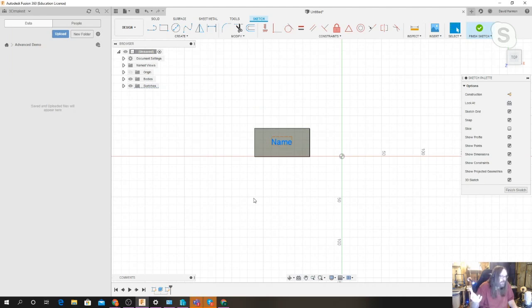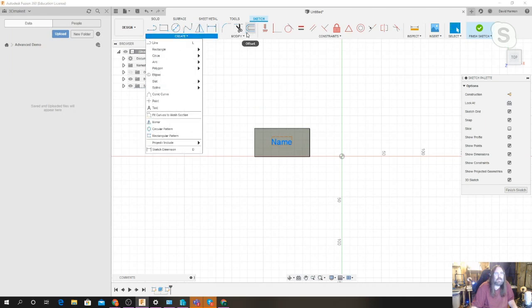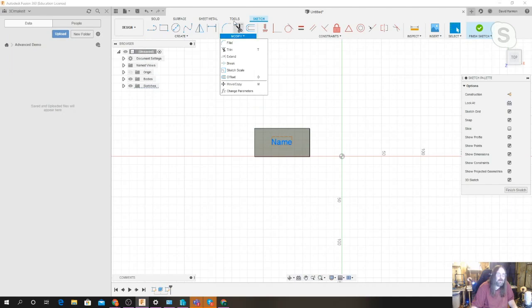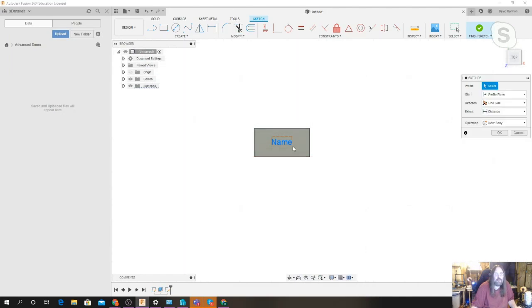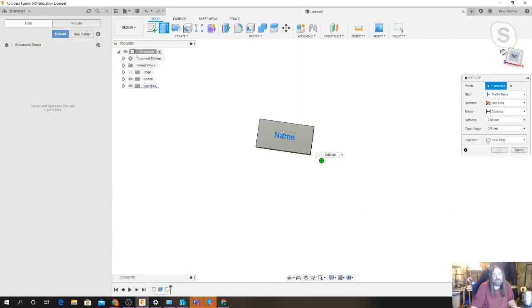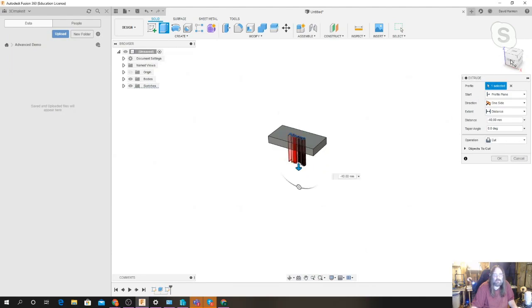So I'm going to hit extrude again. Now when you're inside this menu, you can access extrude very, very quickly. And this works even not in this menu by hitting E. And then it should give you your extrude values, and you get the little arrow back, and you can go inset, and whoa, you can see the line turns red.